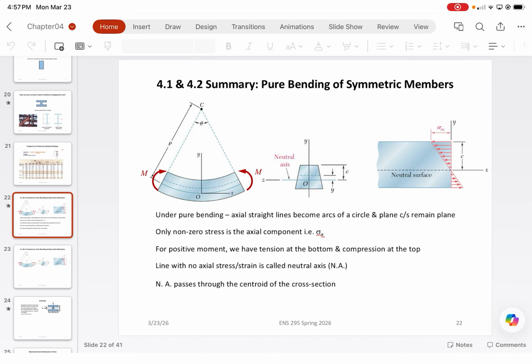Yeah. This is the one part that I think is going to be a little bit more challenging. You have to design it for any possible location. Any location? On the road deck. Yeah. So imagine as if it's a moving load. Generally, for bridge design or in other structures where you may have an anticipated moving load, you need to design for the load to be at any particular point.